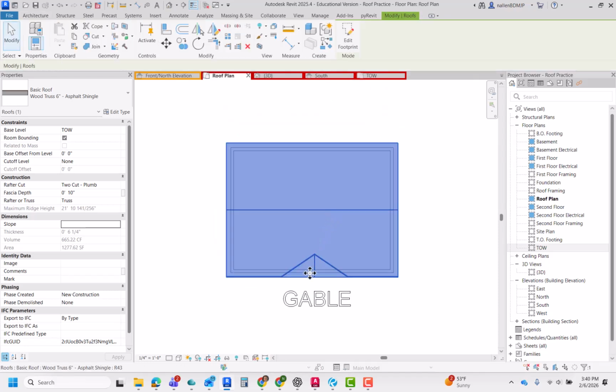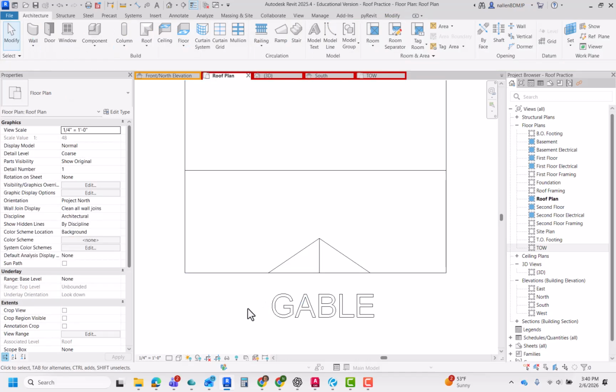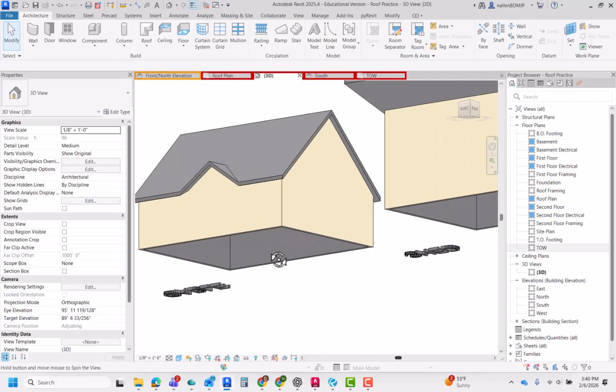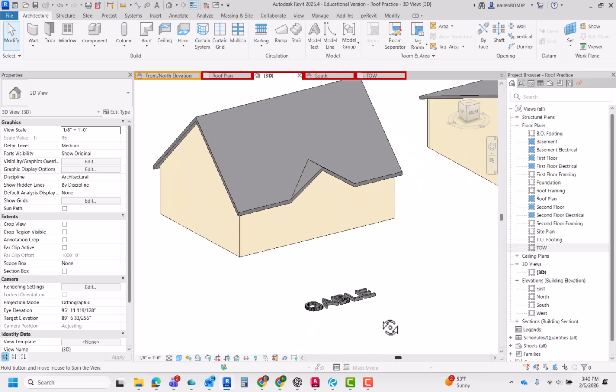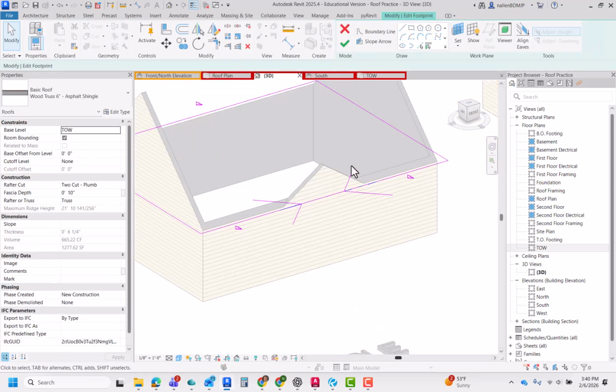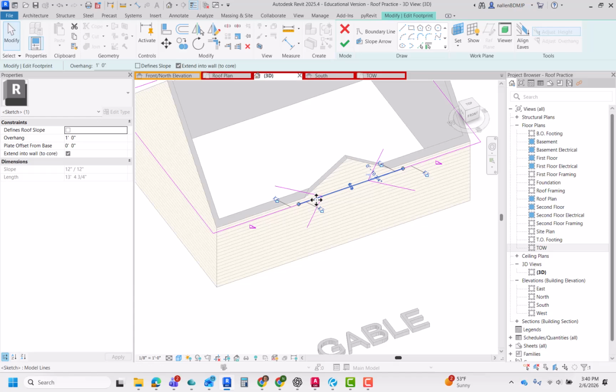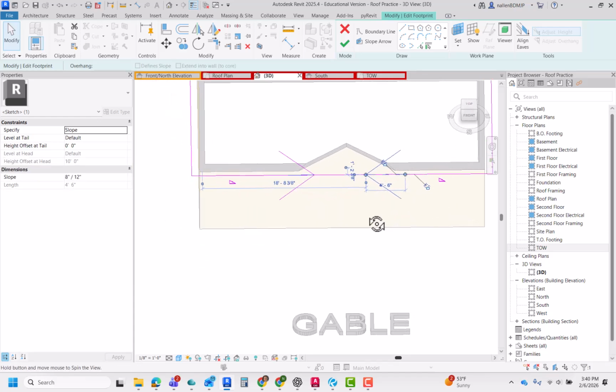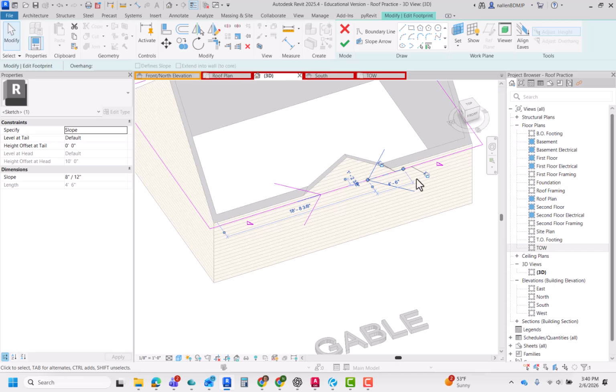And you can see from my plan view that I've got new shapes in there. What did they do exactly? Just what I wanted. I've got a little gable right here in the middle. Okay, one more time just to show you. This is its own distinct line without slope. And the slope arrows do something different. They tell it to start sloping upward at those intersecting points.